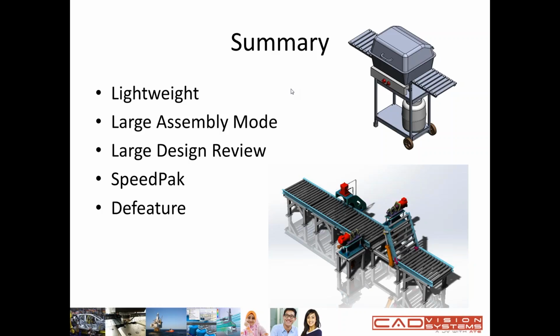SpeedPak is a configuration that reduces the file size of a sub-assembly by reducing it to selectable faces. We select the face or the component, so we can suppress all the other components which we didn't select. About the feature: if you use the feature tool, we can remove the details from a part or assembly to simplify the graphics and improve our performance. So basically this is what we will see for today.